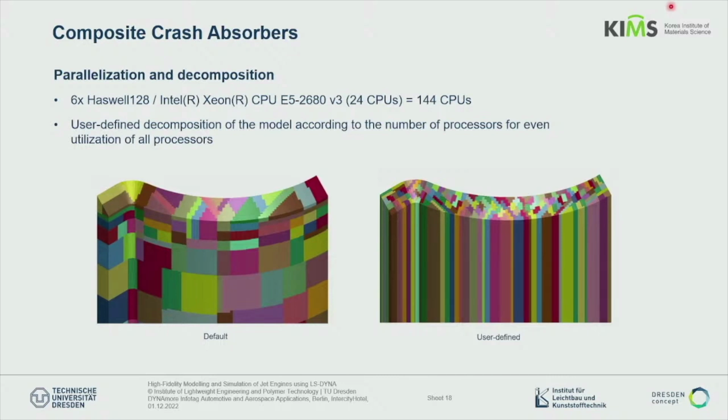So you want to have a nicely distributed, decomposed net to have the computing power well used, and we learned that such a user-defined decomposition helps a lot to reduce the communication and the computational time in comparison to the more automatic or generic one. This helped a lot to get the simulation running well.